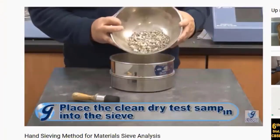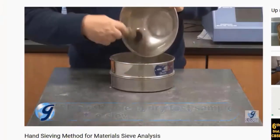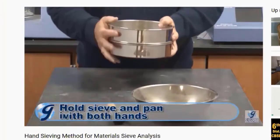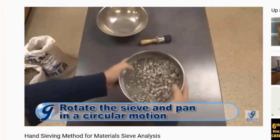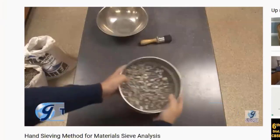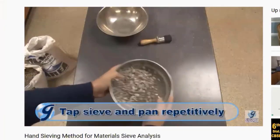Now, place the clean, dry test sample into the sieve. While holding the sieve and pan together in both hands, sieve the material in a gentle circular motion. Still holding the sieve and pan within your hands, use your hands to repetitively tap on the side of the sieve to prevent sample blinding.